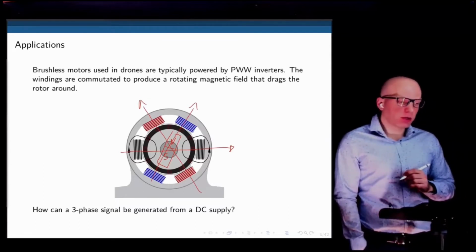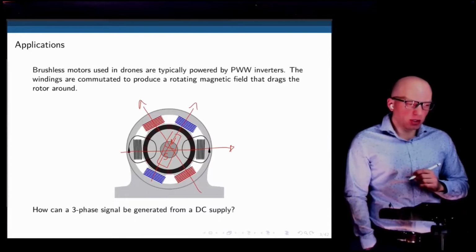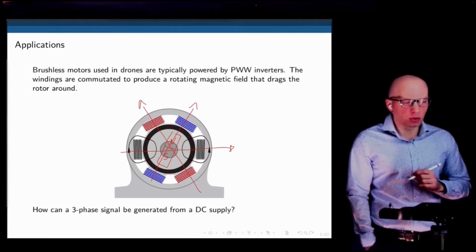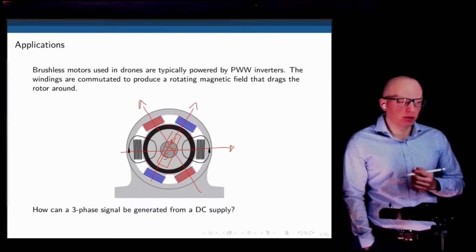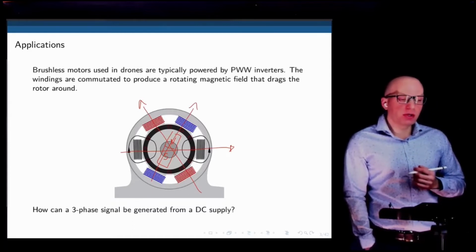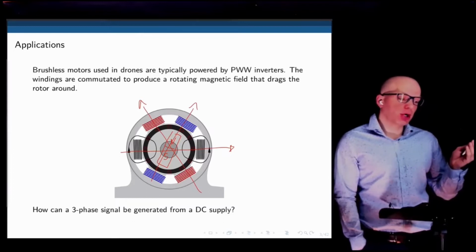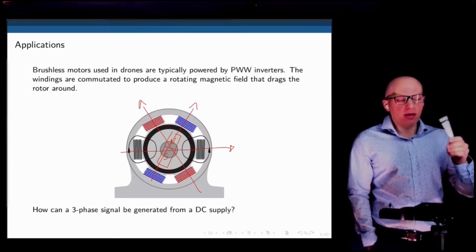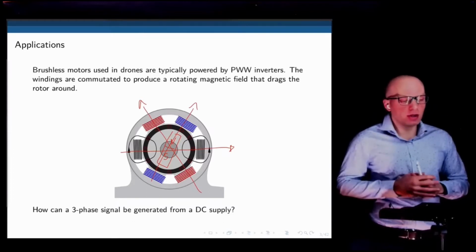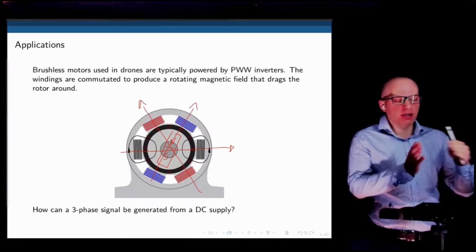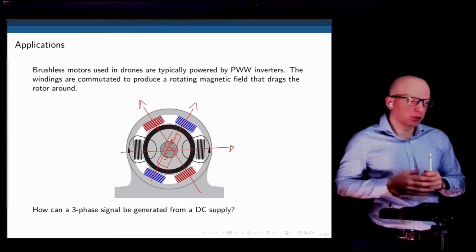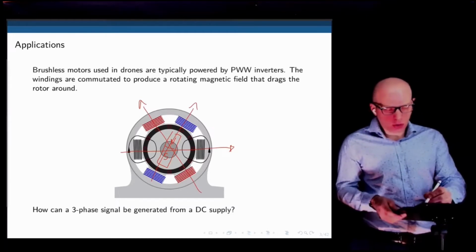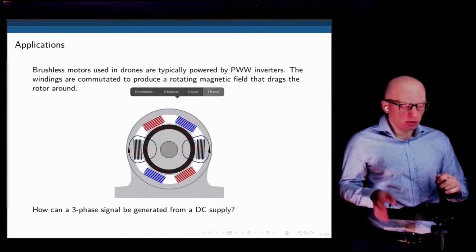The problem that we can clearly see here is that we can only have this vector pointing towards a finite number of directions, in 6 different directions, which means that the rotor would have to jump from one phase to another, and the control would be a bit choppy in that regard because it's not very smooth. We can only have a resolution that is limited by the number of coils that we have inside of that rotor.